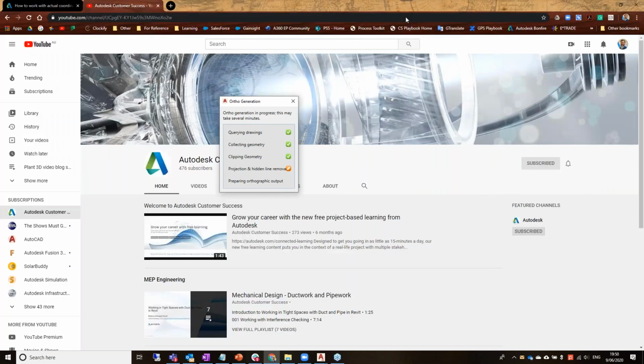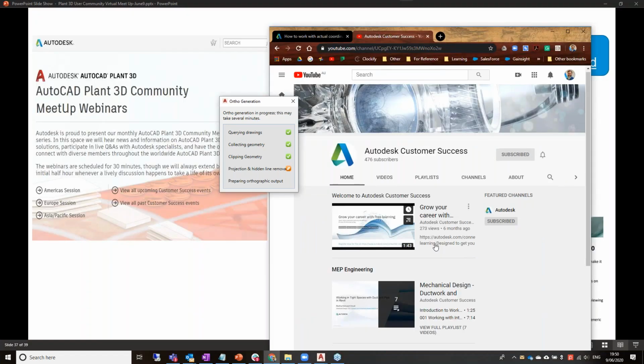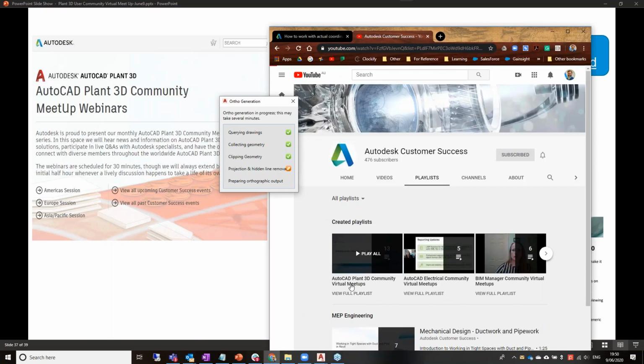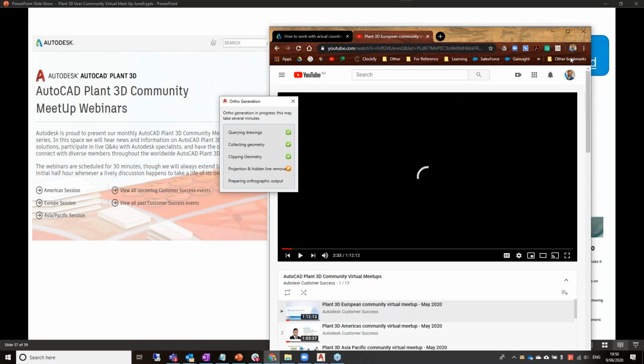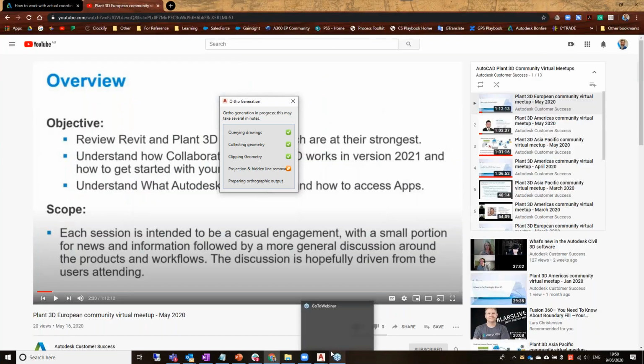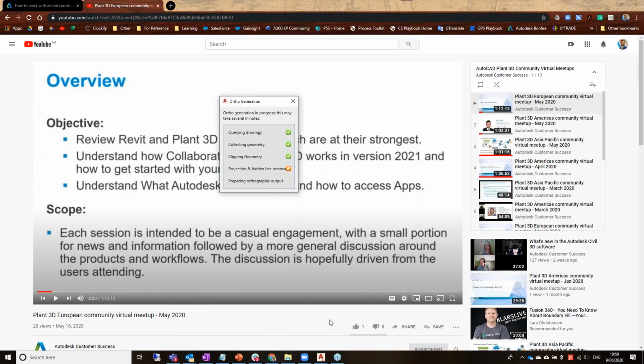Just in between, David, we have an interesting question from Herman. He said you showed advanced steel drawing in the Plant 3D collaboration project. How do the additional files which advanced steel needs synchronize with the collaboration project? It doesn't. Short answer, it doesn't. It is just the DWG. So there's a much longer discussion there around how to deal with advanced steel.